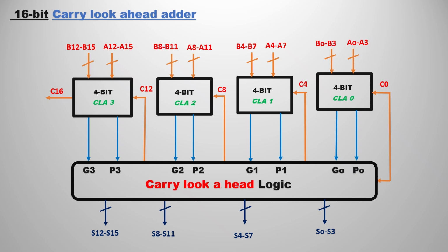If you go back and observe the previous one, we discussed that the previous carry is also passed to the second CLA. That is the main logic or delay. We use the CLA to reduce the propagation delay, but again we are passing the carry to the next CLA, so it produces some delay. For a small rectification, we add another logic block, that is a CLA block.